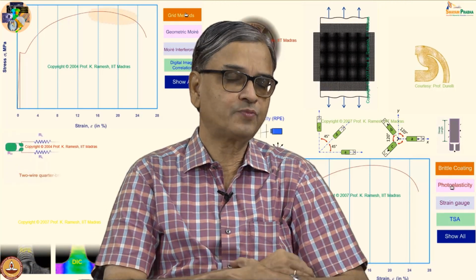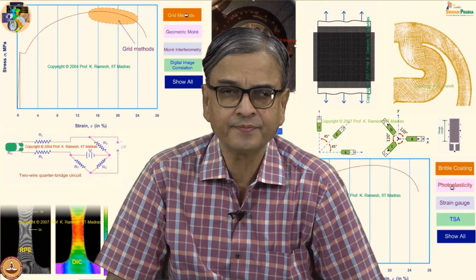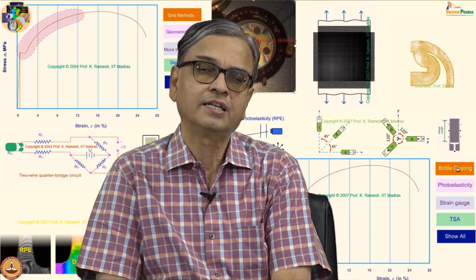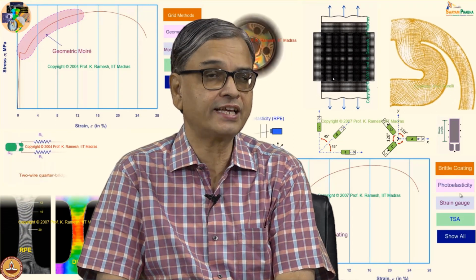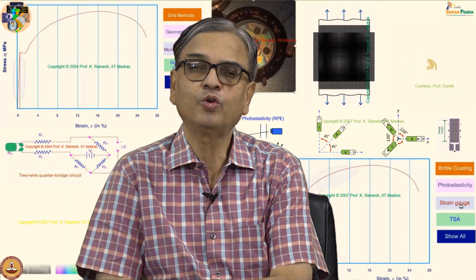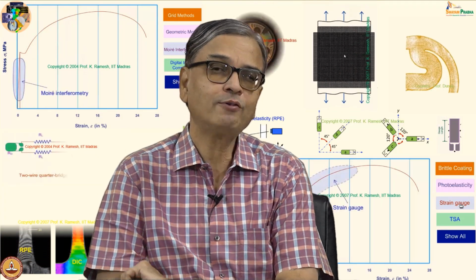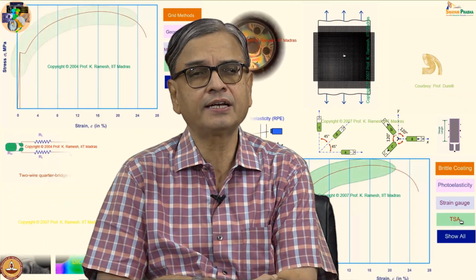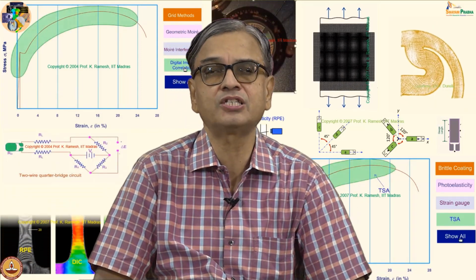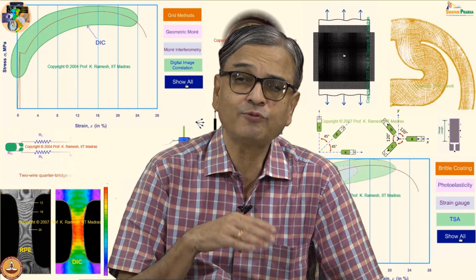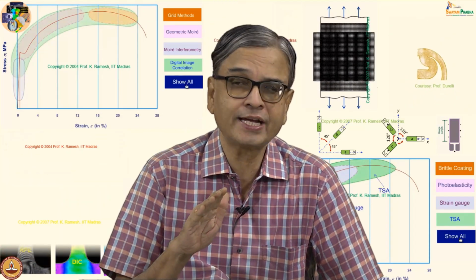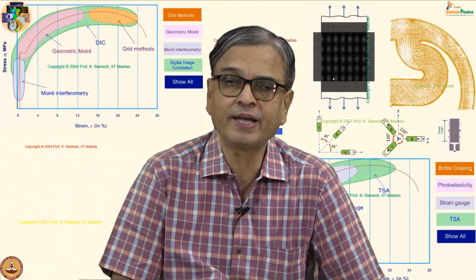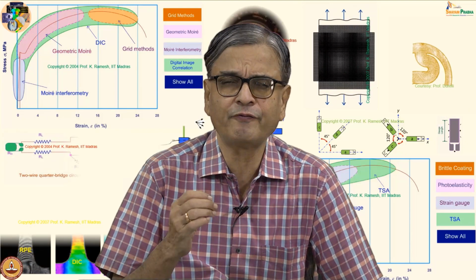See, in the last class we have learnt what is strain at a point. When you say strain at a point, you recognize that you have to refer to state of strain at a point. And when you look at in 2 dimensions, you have 3 components, fine. And we have also looked at, when we talk about infinitesimal strain, the quantity was very small. We are talking about in terms of micro strain, and we said it is 10 power minus 6 millimeter per millimeter. It is a very small quantity.